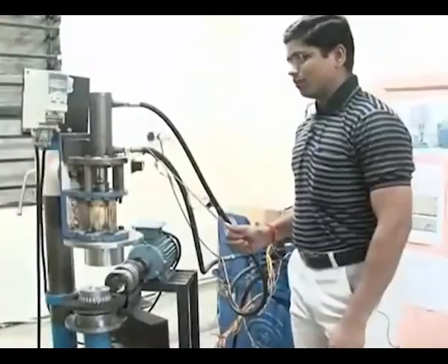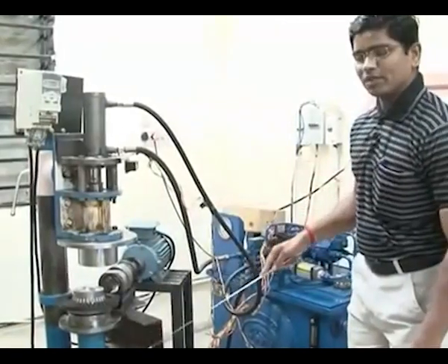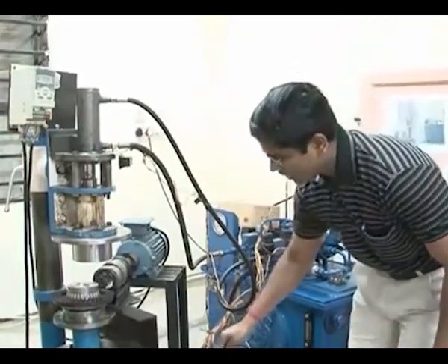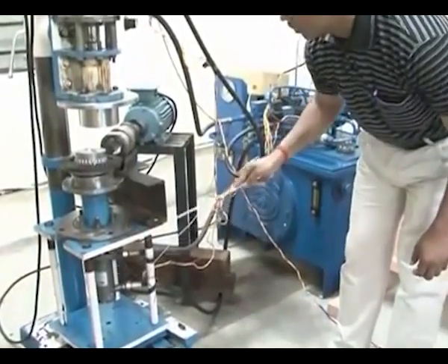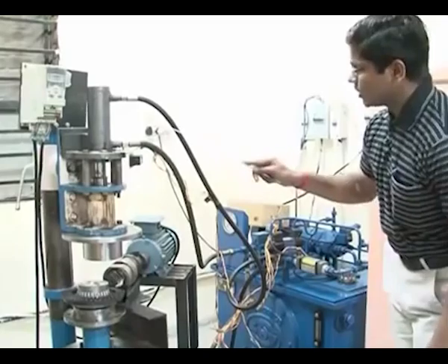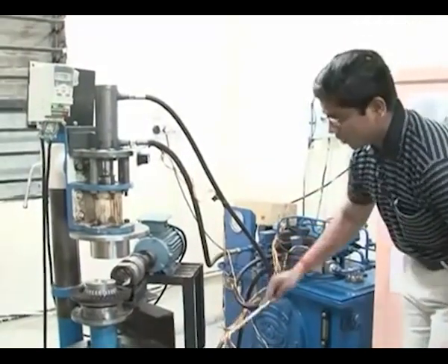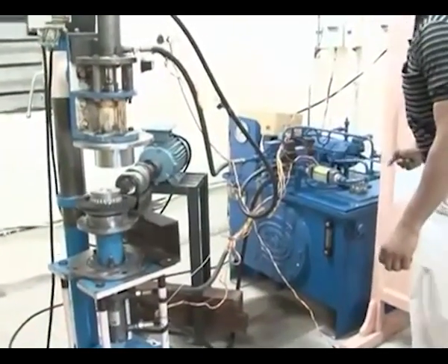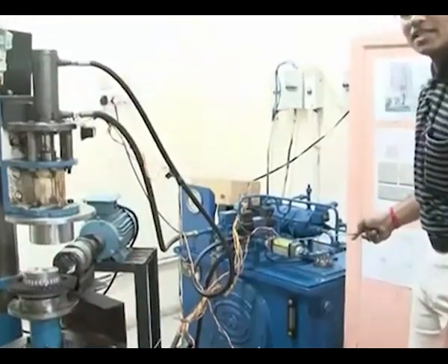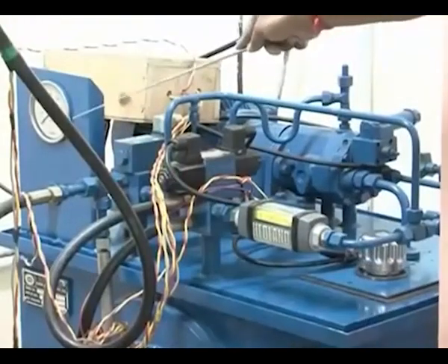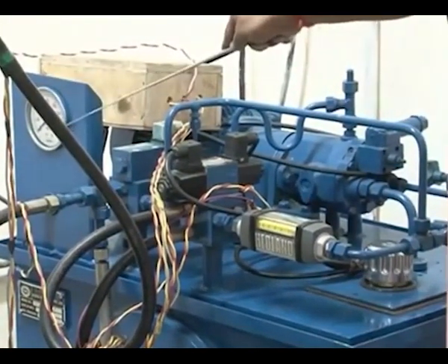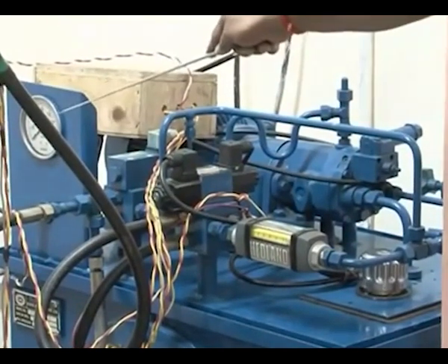So coming to the abrasive flow machine, it is a double acting abrasive flow finishing process. You have upper hydraulic cylinder and lower hydraulic cylinder, and lower medium cylinder and upper medium cylinder. And these two hydraulics, top and bottom, are controlled by a hydraulic power pack. This is the hydraulic power pack, where you can set the extrusion pressure. Here you can see the extrusion pressure. You can go to a maximum extrusion pressure of about 140 bar, that means 14 megapascal.